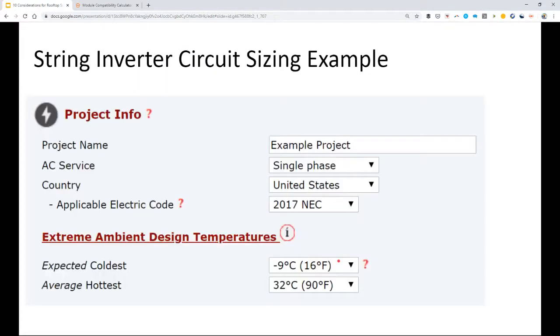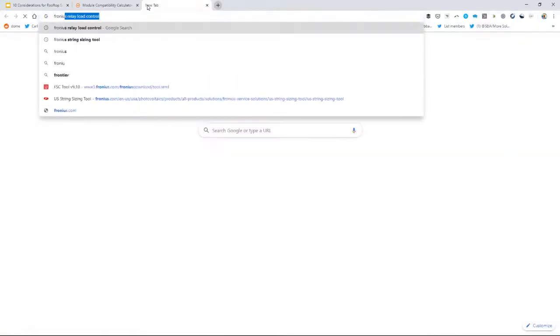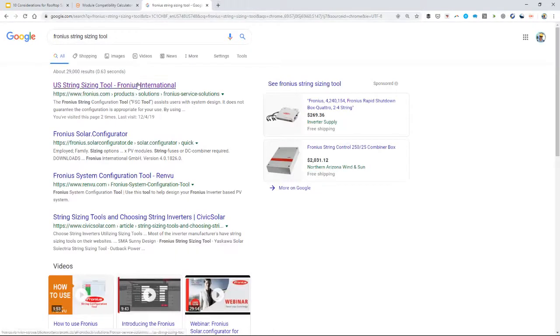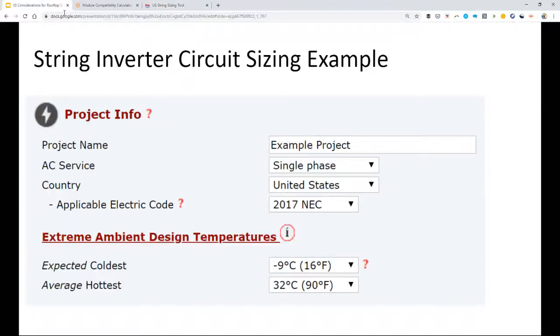Experienced solar installers will opt for DC optimizers with string inverters, which brings the code-compliant and shade-tolerant advantages of microinverters along with some cost savings. Microinverters cost more than DC optimizer solutions. The compatibility of a solar panel to a particular DC optimizer is similar to the compatibility of a solar panel to a microinverter.